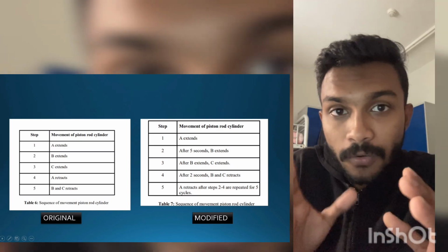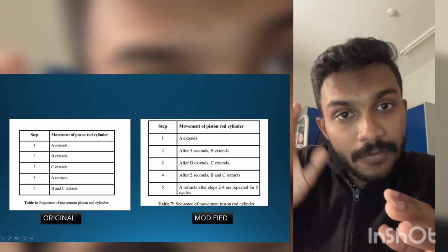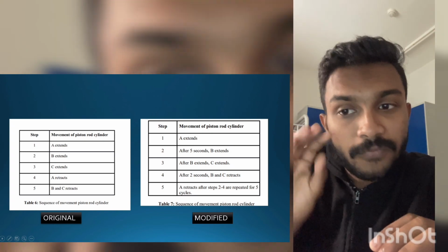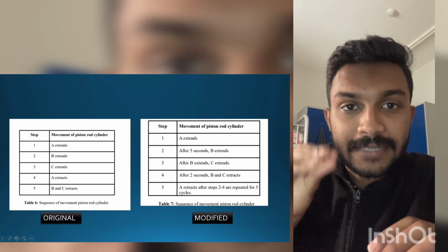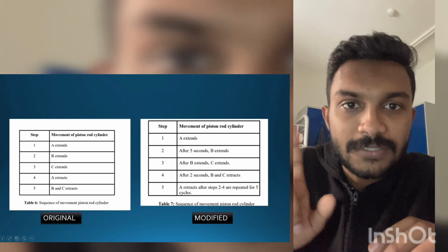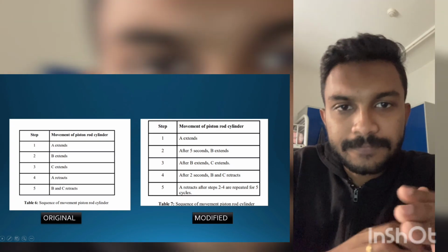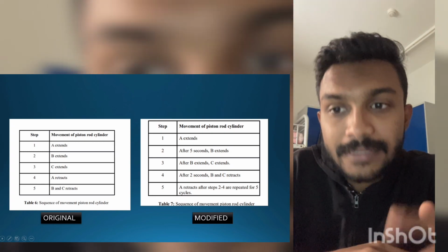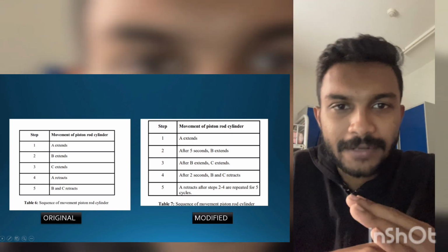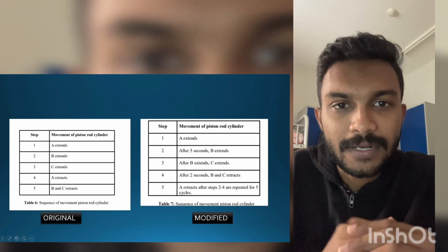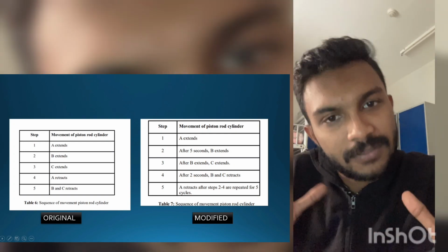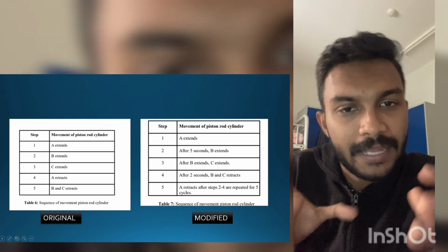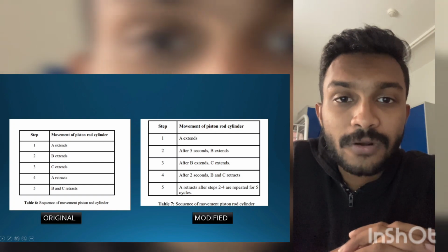So for example, if in a container they need 10 canned sardines, they can set the counter as 10. Now, for example, I just put 5 cycles, which means only 5 canned sardines will be put inside the first container. Okay, so once steps 2 till 4 are completed, then only the A will retract back to the original position. So that's when the cycle or the process is complete. Once complete, the worker can collect the basket and give it to the sorting team for packaging.